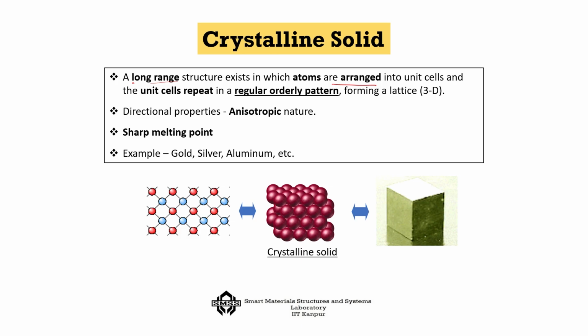One of the plus points is that the crystal structure shows a high degree of anisotropy. You may consider it a plus or a minus. The plus is that in one direction it will be extremely strong and in another direction it may be very weak. So we have to orient the crystal towards the direction where the maximum load is going to come into the system. In that sense, anisotropy will be of help for us.